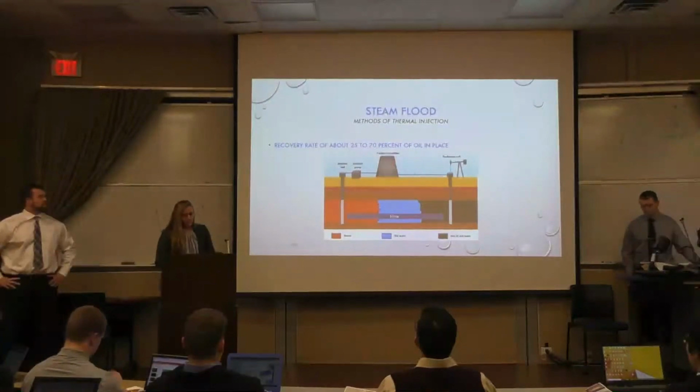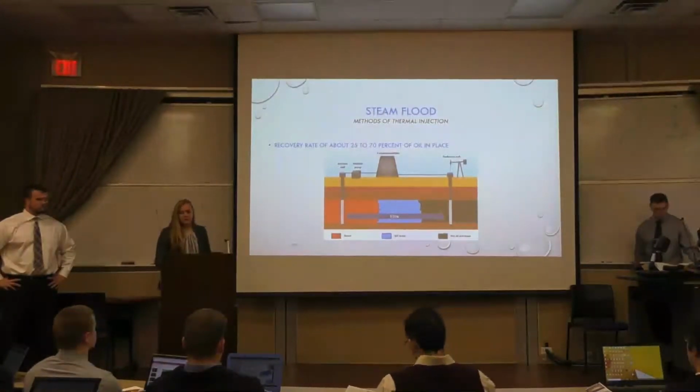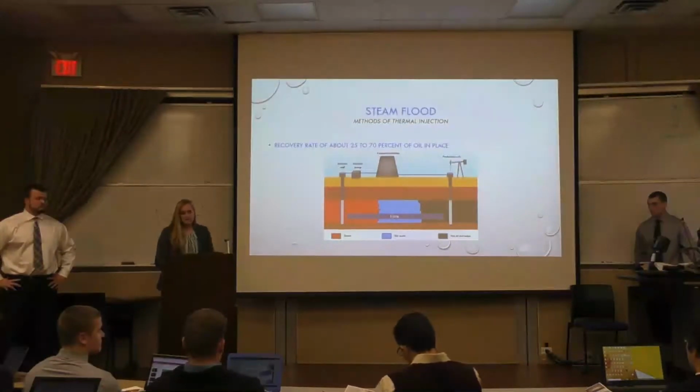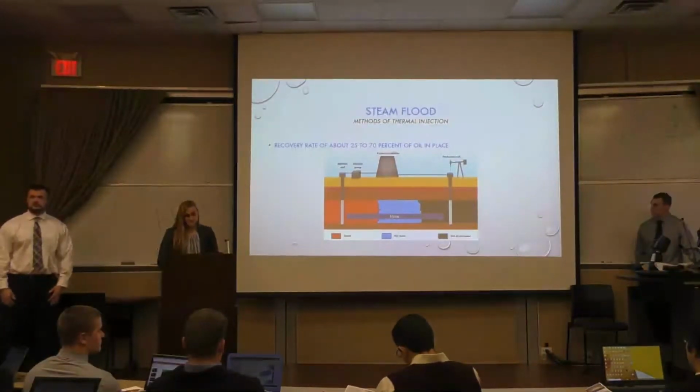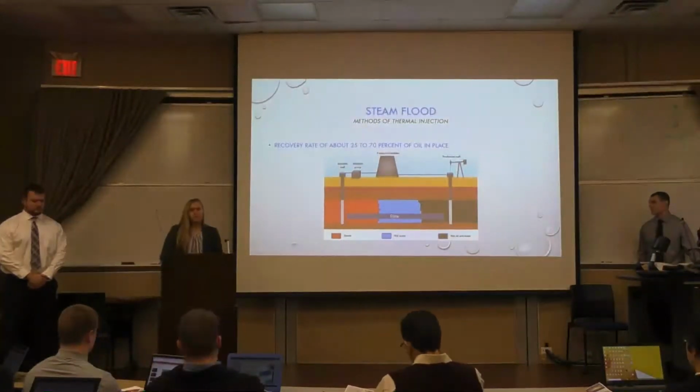In this form of recovery, steam is constantly injected into your reservoir through the injection well. This is done to heat the heavy oil and to improve the viscosity. A water drive also pushes the oil towards the producing well when the steam condenses into hot water.